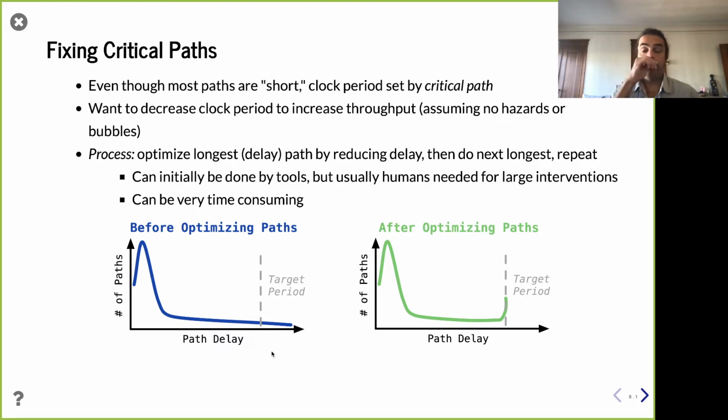And you get a listing of, it goes through this component, this component, this component, this component. And sometimes when you see these paths, you're going to be kind of surprised, but then not that surprised. You're like, wait, where is it going? And you look at your design a little bit and you're like, oh, wait, that makes sense. That's a very long path. That's going to be perhaps a long wire delay, or it's perhaps going to be touching a lot of things. There's some things that are sometimes very subtle where it's like, oh, wait, this particular signal I'm using, it's going through so many things. I didn't think of it this way. How it's going to go through so many things, right?